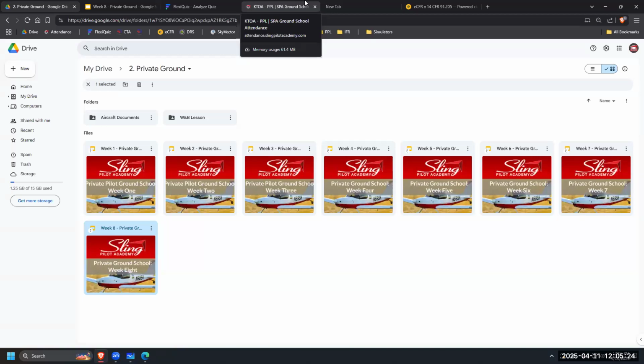That's gyroscopic precession, right? By lifting the tail, the force will be felt at the tip of the propeller 90 degrees to that point where it has been impacted, causing the plane to yaw. Tip of the propeller, 90 degrees, yaw movement. Obviously, if this propeller was turned the other way around, and you lift it, the force is felt 90 degrees to the right.